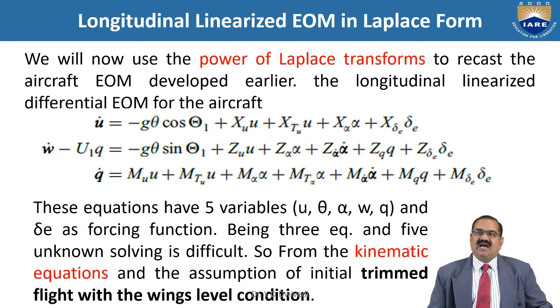In the previous lecture, I discussed the equations of motion in the longitudinal axis. That is the 3 equations. One is the force which is acting in x direction, the force which is acting in z direction, meaning vertical direction, and the moment which is acting with respect to the lateral axis, meaning only pitching motion in which the nose is going up or down. These 3 equations of motion we have been discussing till now.